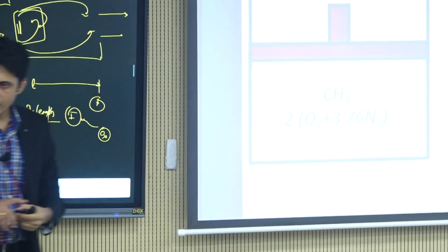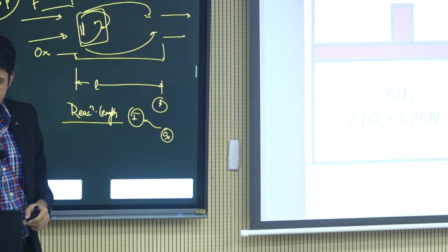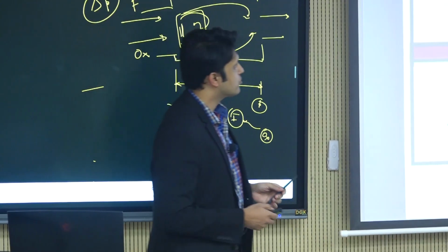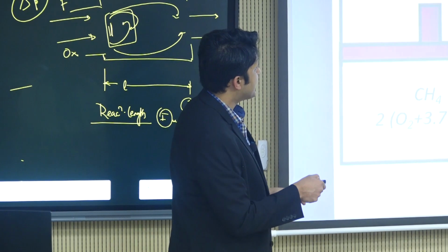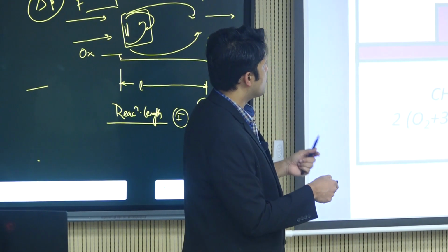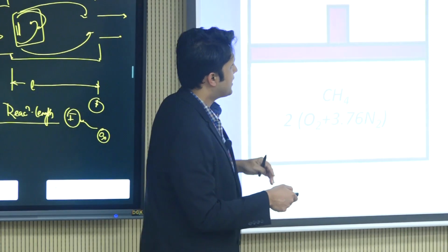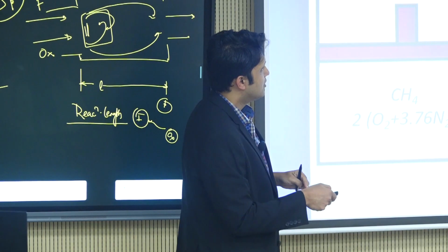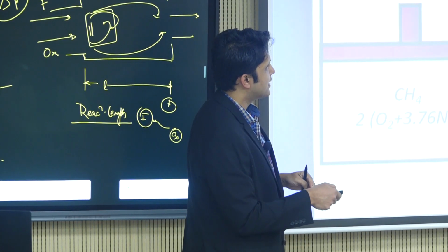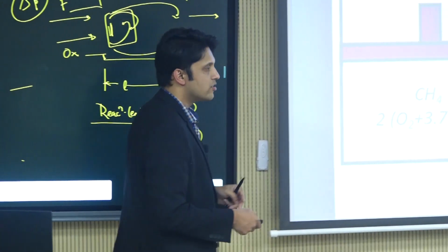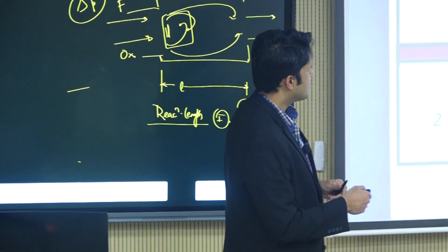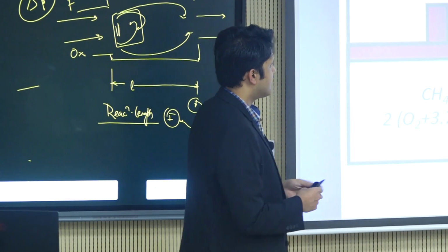So this is straight away the first law of thermodynamics, and if you apply it, the change in total energy is E2 minus E1, where 1 and 2 are state 1 and state 2, equal to the heat added, minus the work done, that is pressure times (V2 minus V1). This total energy of the system has three components.